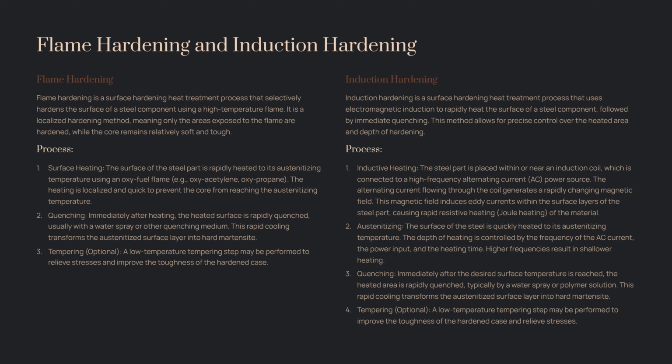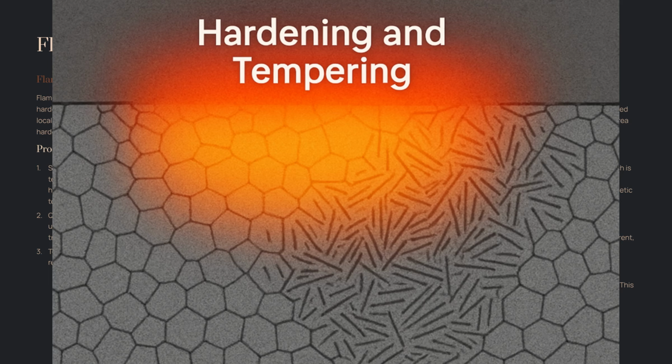Tempering. Optional. A low temperature tempering step may be performed to relieve stresses and improve the toughness of the hardened case. Key characteristics and advantages.